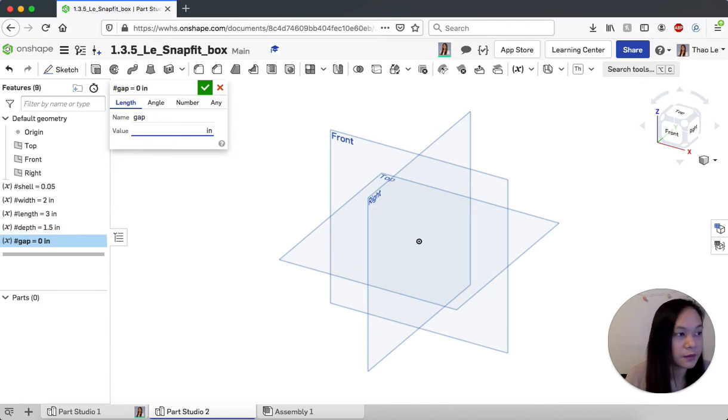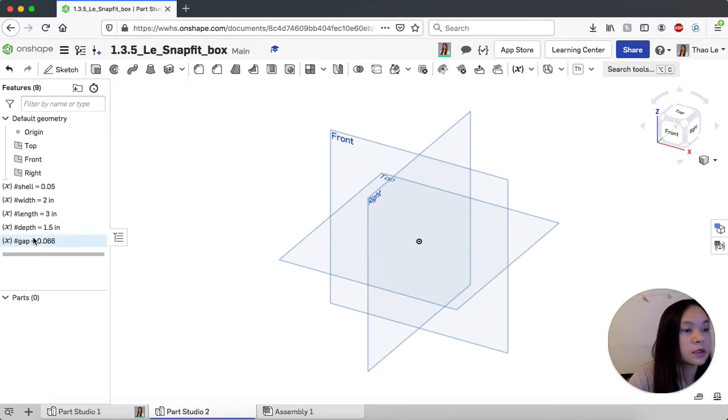So that's going to be from ahead of time. I'm going to say any. It's going to be the shell. Okay, so the shell formula plus I believe I did a tolerance of 1/64th. Yeah, so 1/64th, and you might have to change this based on your printer, but okay, and that should have all of the variables here.